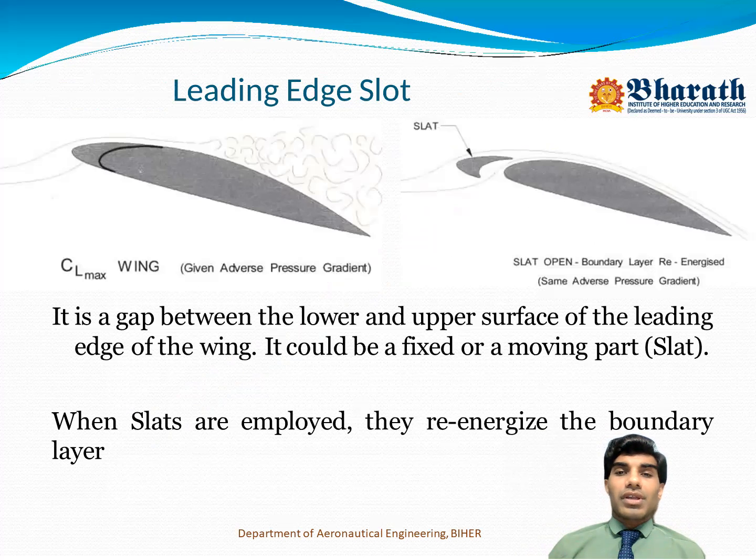Now we will talk about the leading edge slots. We have seen trailing edge flaps and leading edge flaps. Now we are going to see the leading edge slots. As you can see in the first figure, the flow is coming from the forward direction, and then towards the back many vortices and turbulence are generated. At the maximum coefficient of lift, the wing has an adverse pressure gradient.